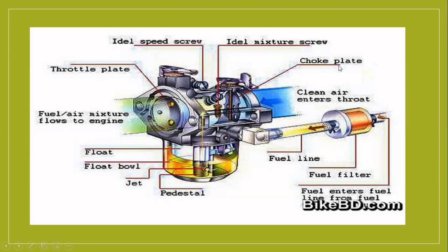When you close the choke, normally the valve is closed. Open means that you apply the choke on the choke switch. There are two, a choke lever and a choke switch. When you apply the choke lever or button, the choke valve will close.